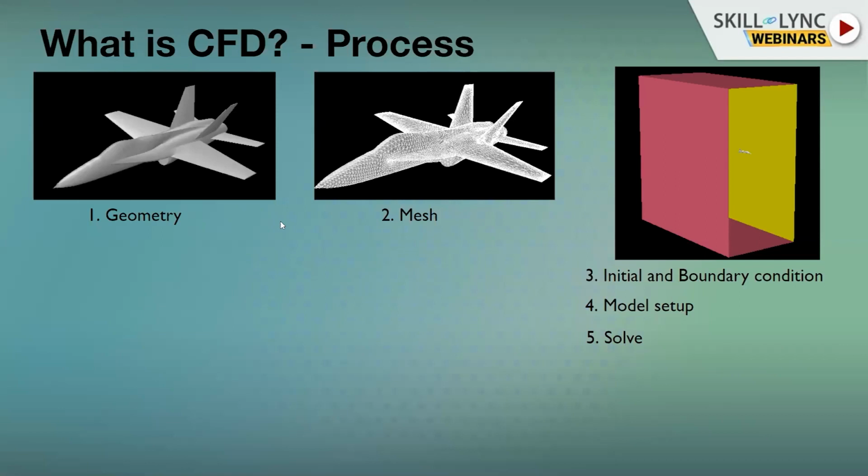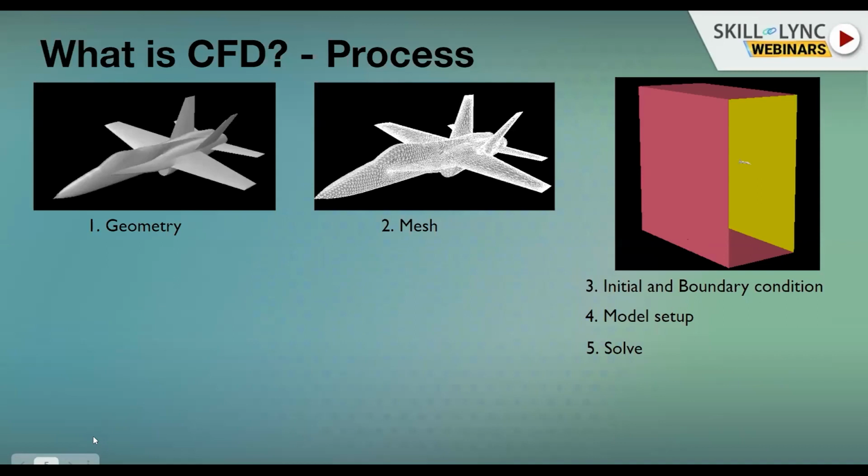Most of the time, if the CFD solution is not converging or has some issues, it could be a problem with the boundary conditions, or sometimes the mesh. And the initial condition is critical for some cases, but most of the problems we solve are initial condition independent, so it's not very critical for the final solution, but it influences the convergence rate.